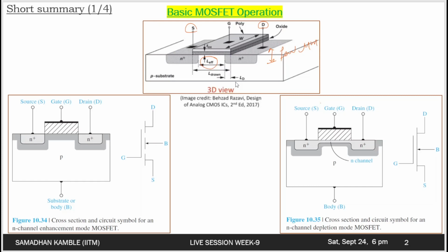It is not enough to have a piece of semiconductor; we have to connect it to the external world, for example to relate it to another transistor. How do we connect? If you directly put a piece of metal, it will have a contact resistance, as we have mentioned earlier. To avoid that, we can engineer these contacts in such a way that one contact would suffice, but we typically make more contacts to minimize the contact resistance. So this is basically how a MOSFET structure looks. This is the length, this is the width, and these are the contacts, the gate, and the substrate.